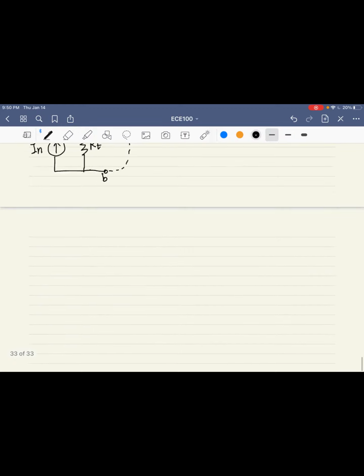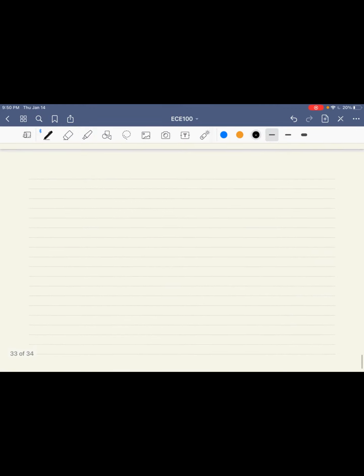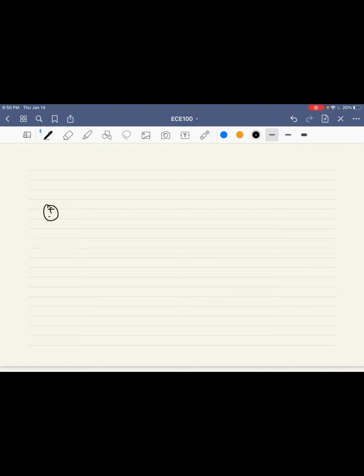And let's give you a brief example about its capability. For example, we have a circuit like this. Just observe it. We cannot solve it by only applying division laws, right? We need to use node voltage or mesh current analysis. And they also have two types of sources. We don't want that. So in this case, we can select this point at terminal A, this point at terminal B. And then we can try to change the left part into a Norton equivalent.